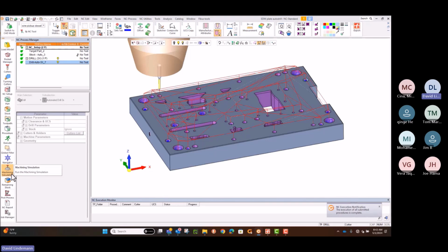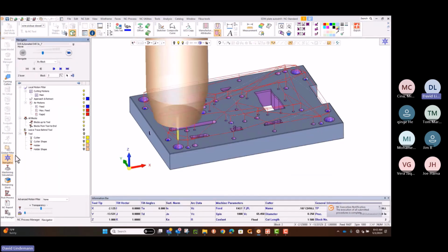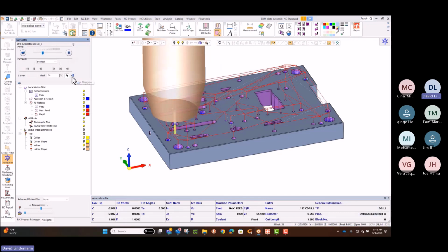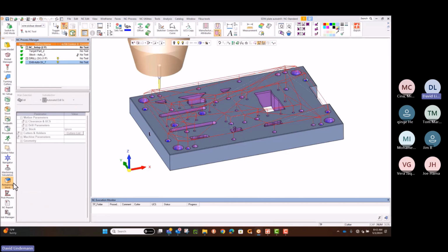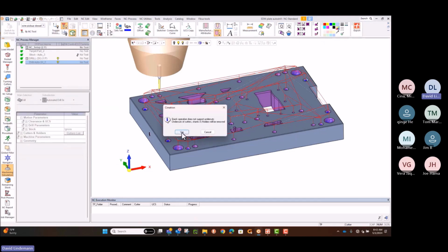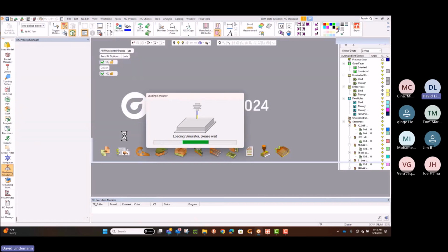If we simulate running the spot drill first here, we can see how it takes those different types of tools and groups them. If I wanted to spot here and then here, it's not doing a tool change, running through one hole, then coming over and doing all the tool changes on the next hole. It's gone through and made it smart. With each of the times that I run something, I can check my remaining material. We can use the whole machine if we want when we do the simulation. It's whatever makes sense to you to help you get the job done quicker. So here I'm saying, just give me the quick simulator.